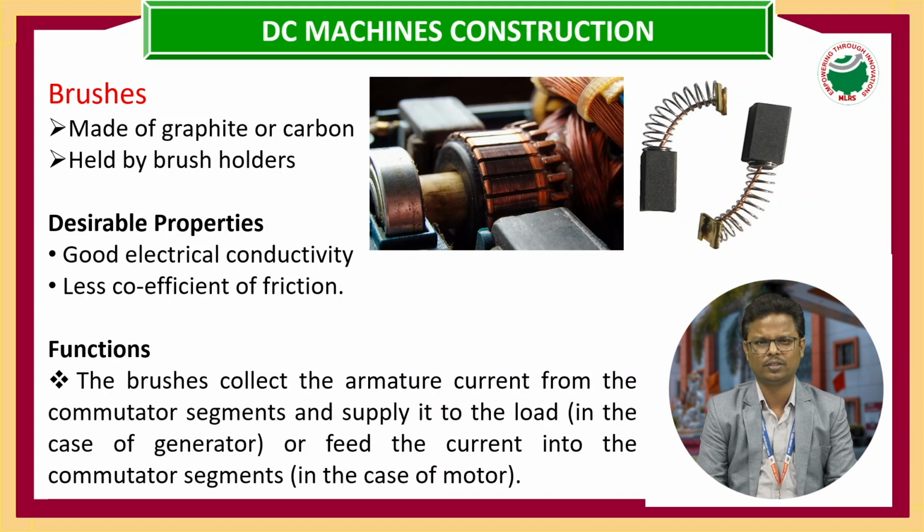The function of the brushes is to collect the current from the commutator, and the brushes can be changed according to the rating of the devices. Here we have brush holders. According to the increasing size of the machine, the number of brushes will also increase. And here we have brush holder springs, which keep the brushes in contact with the commutator.